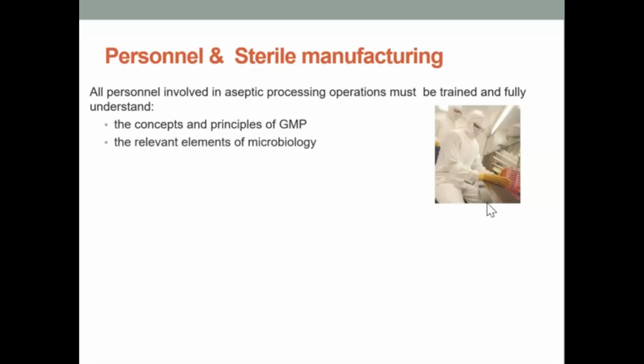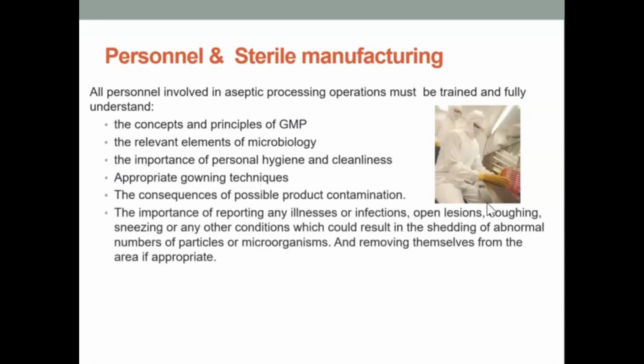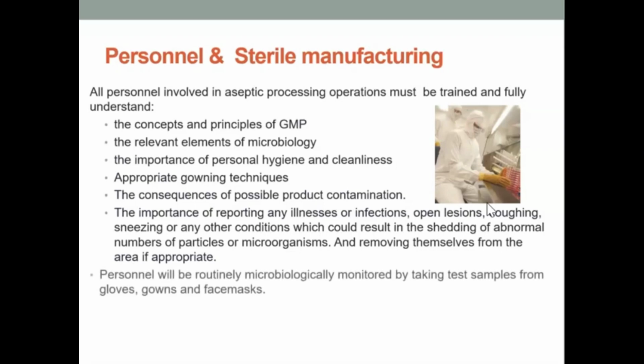They must understand the relevant elements of microbiology, the importance of personal hygiene and cleanliness, appropriate gowning techniques for the area in which they work, the consequences of possible product contamination, the importance of reporting any illness or infection, including things like open lesions, coughing, sneezing, or any other conditions which could result in the shedding of abnormal numbers of particles or microorganisms, and in that case they would need to remove themselves from the area if appropriate.